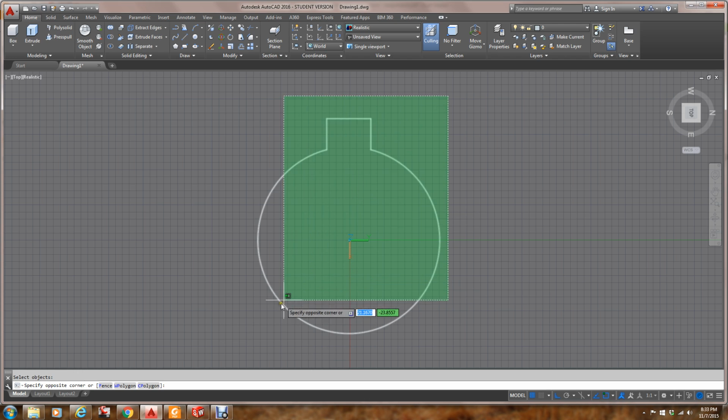If I highlight this, you can see that this is a bunch of different objects. Here's a circle or an arc, now here's a line, there's a line. And if you remember in my instructions, for you to change a 2D object to a 3D model, it needs to be closed and it needs to be one object. So in this case, these are all separate.